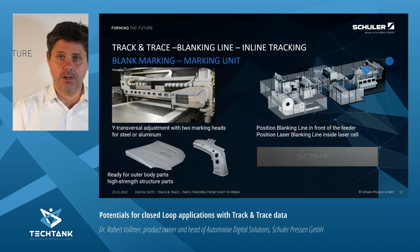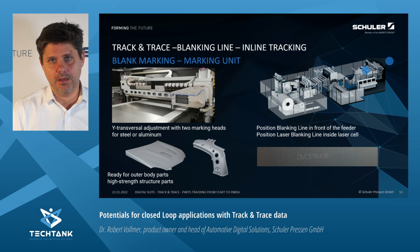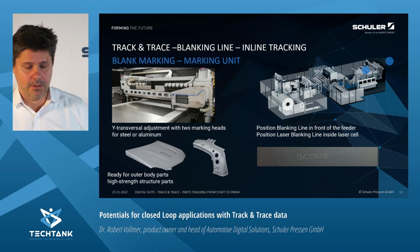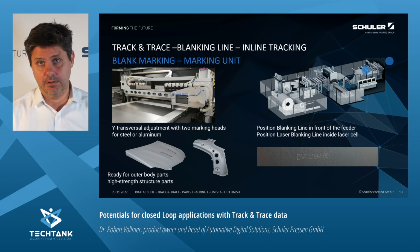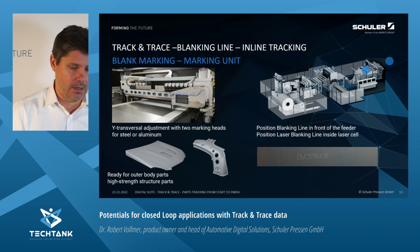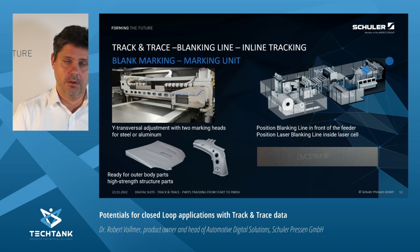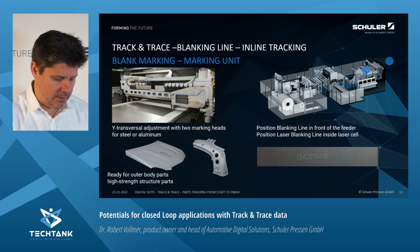This was the challenge in this project, that we need a really small marking and also the possibility to do a marking of the shell parts. The specification here is that the marking must not be visible after the painting. So in this case, we reached that goal with a slight alphanumerical code, which has only a depth of a few microns, but we are able to read this code very safely in the press line and in the other stations afterwards. So it's no problem to do the identification of the blank afterwards.